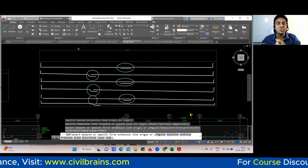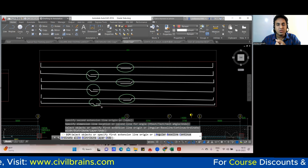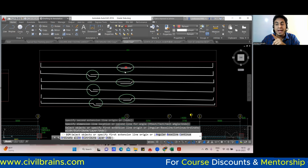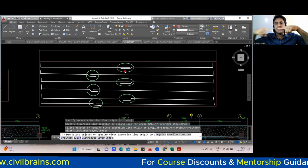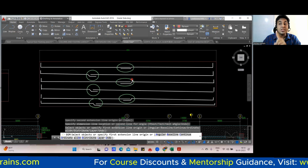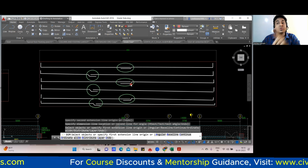You're getting my point? No, this should be equal. I mean, it should not come parallel. All 6 bars should not be lapped here. Alternatively, this will lap here, next bar lap here. After that, here in this way. So that is what you need to understand. But cutting length remains the same. This point is from execution point of view.